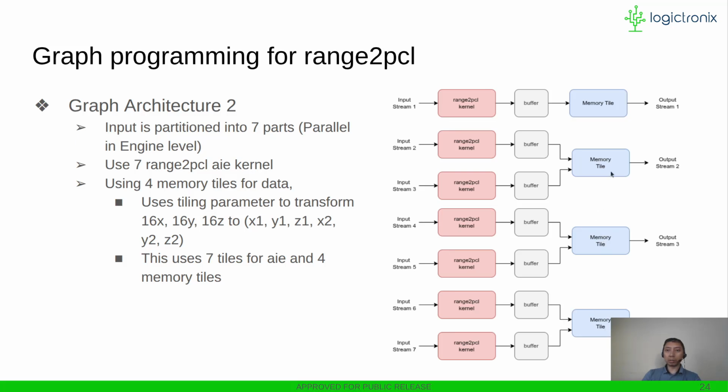Memory tiles are just tiles which consist only of memory blocks, and it is 512 kilobytes. It can be accessed by multiple AI engine compute tiles.